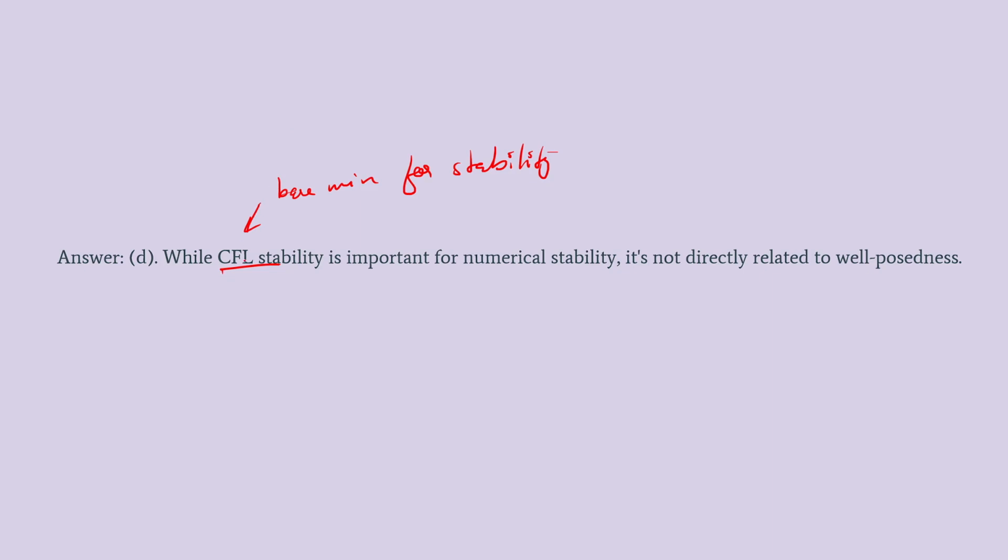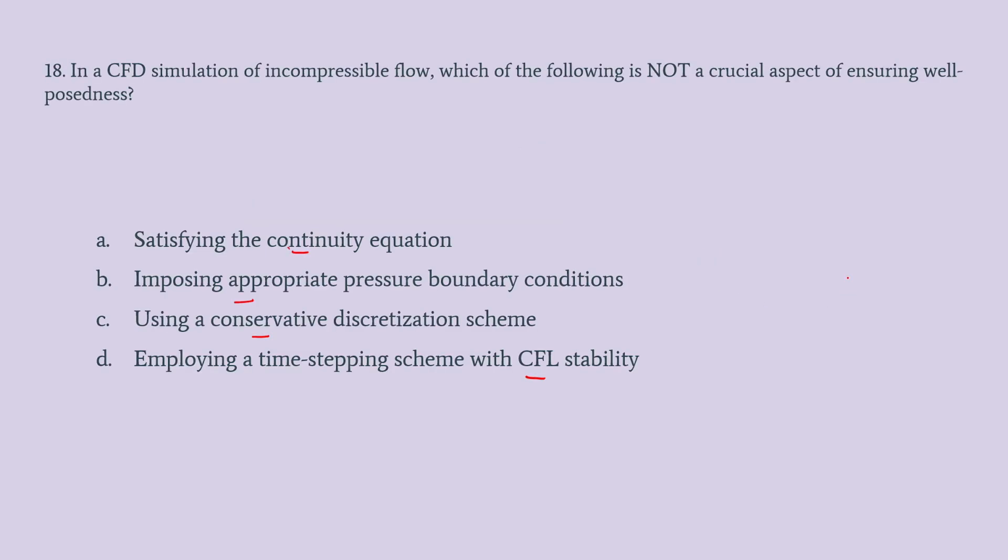In CFL stability criteria, what we have to think is how the scheme will be stable for a given problem, and that is not directly related with the well-posedness. The other things, satisfying the continuity equation, obeying the boundary condition, and the conservative property, are all related with well-posedness.